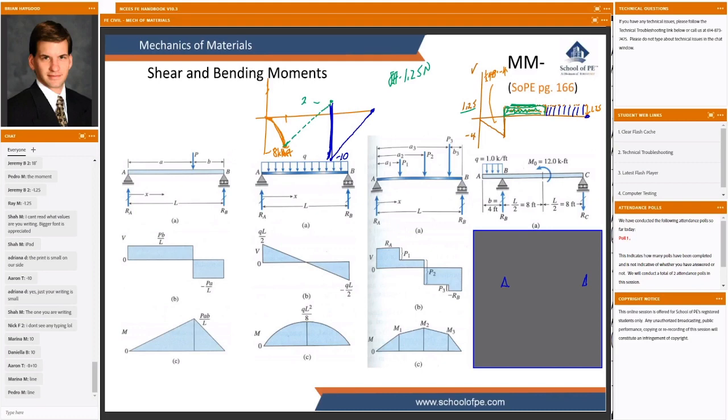I think the left-hand side would be tilting downward like that due to that distributed load. And I think the rest of it's going to be bowed upward a little bit, but at the 12-foot mark, I'm going to see a twist in the beam.